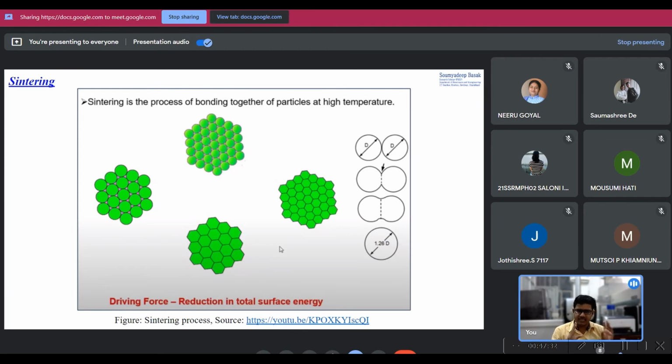You can think of sintering as a kind of burning process. For our hydrogel purposes, or in the case of ceramic sintering, it can be in the 300 to 500 range. The temperature can vary. For our purposes, it is just to burn out the scaffold, whatever polymer scaffold we have used for giving it the structure. It is a burning out process, and to fuse the ceramic material into a single phase, right?